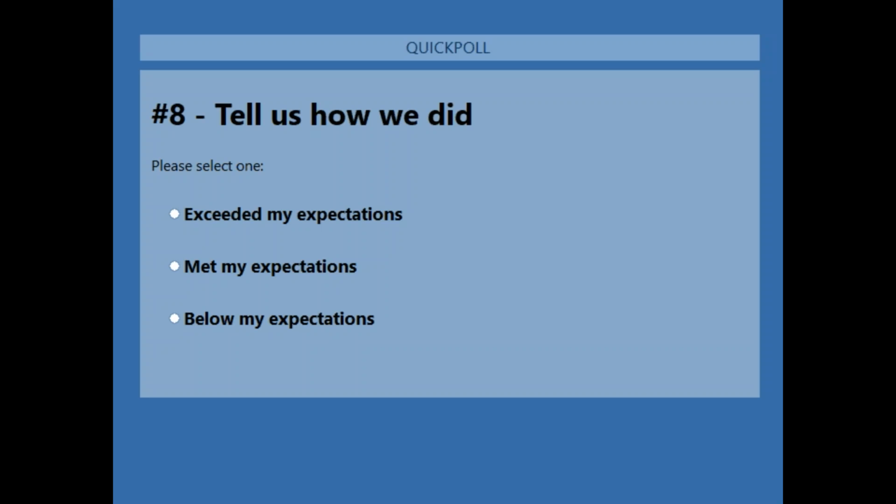If we know we have a 10-ton rated evaporator, and this is all when we build the evaporator. When we build an evaporator, we actually build the number of rows, the number of fins per inch, the face area. And once that evaporator is built, the builder program spits out a tons per circuit. So if I know I've got a 10-ton evaporator, like I said before, and I've got 5 distributor tubes, I can take my 10 tons and divide it by 5 and figure out my tons per circuit.